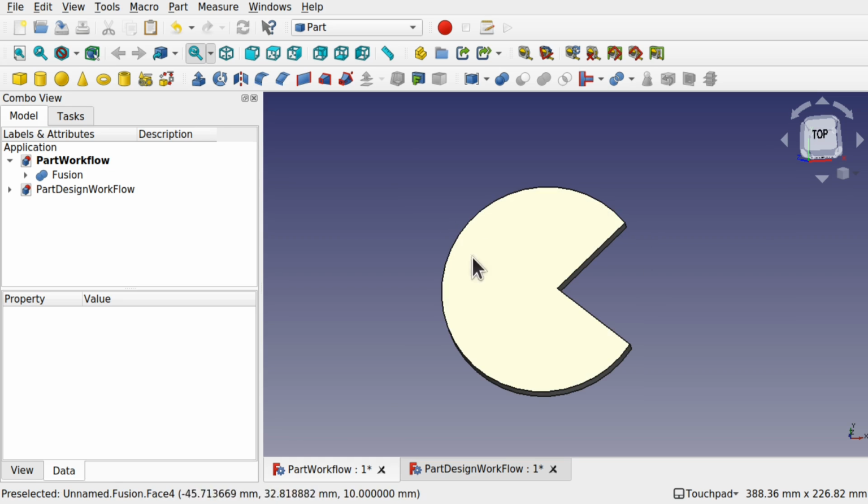The techniques that I showed you with the different ways of creating the same object are useful for different applications. So you'll come across applications as you're using FreeCAD, as you're starting to understand it, where you'll use a Boolean, where you use a Revolve, where you use the pad, the pocket, etc. It's well worth, when starting out with FreeCAD, to create a very simple model and then look at different ways of taking that model and changing those workflows, changing those techniques, and starting to really understand how FreeCAD works.